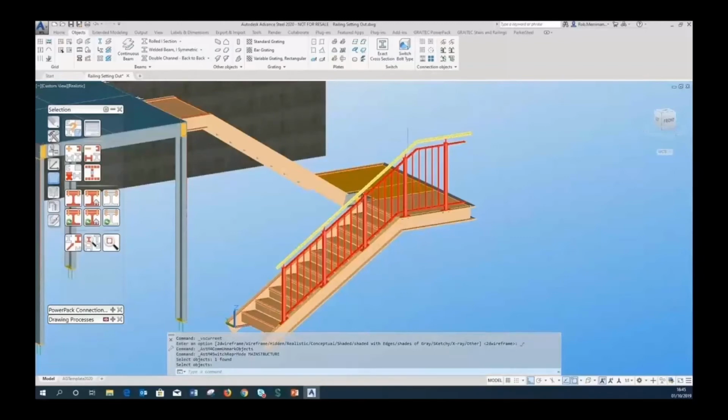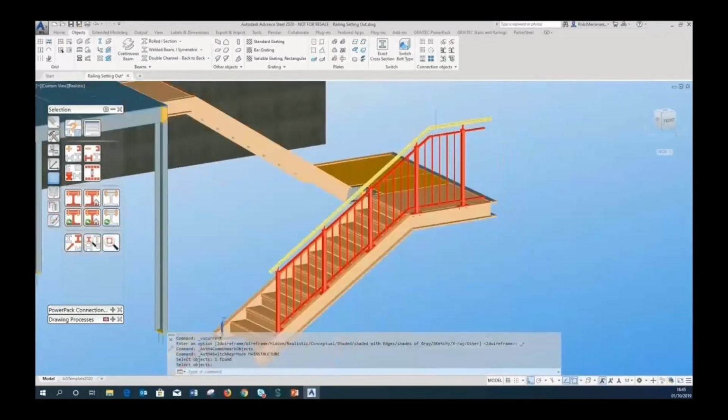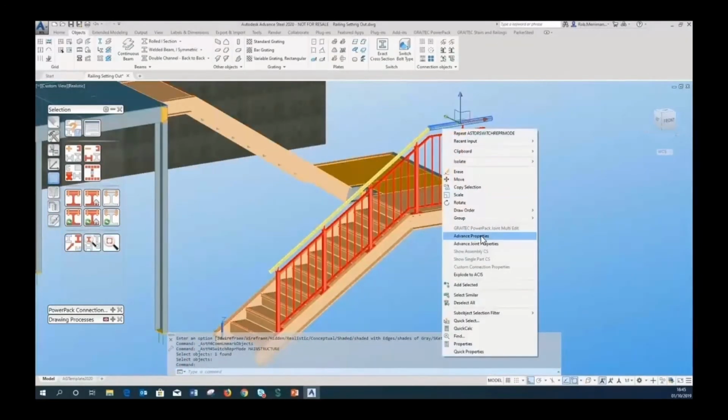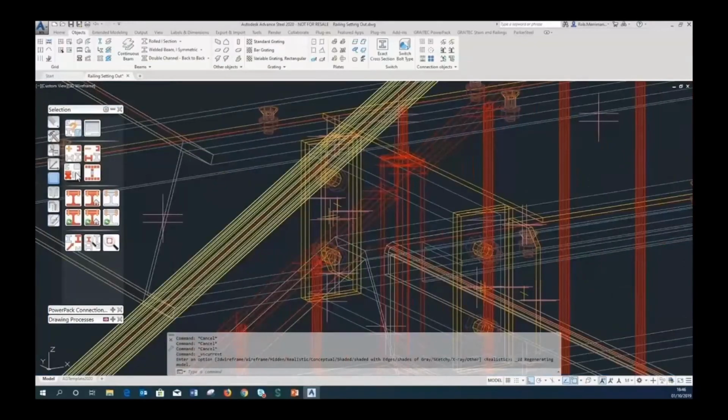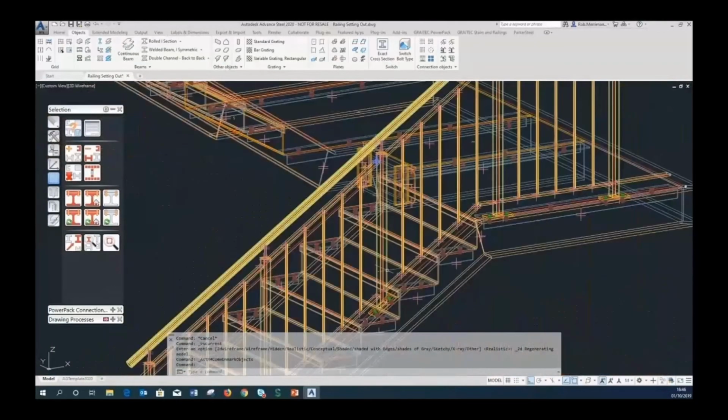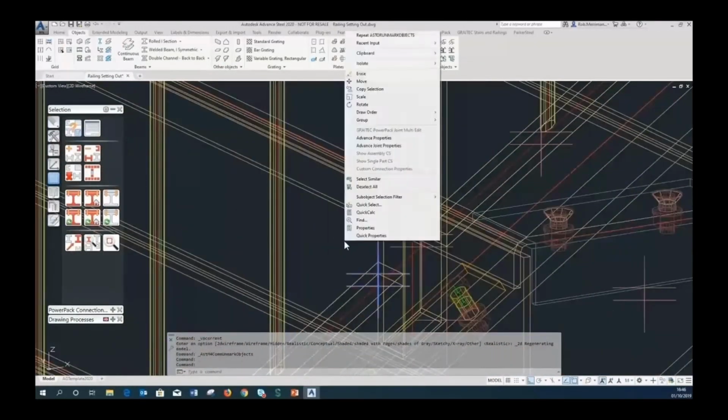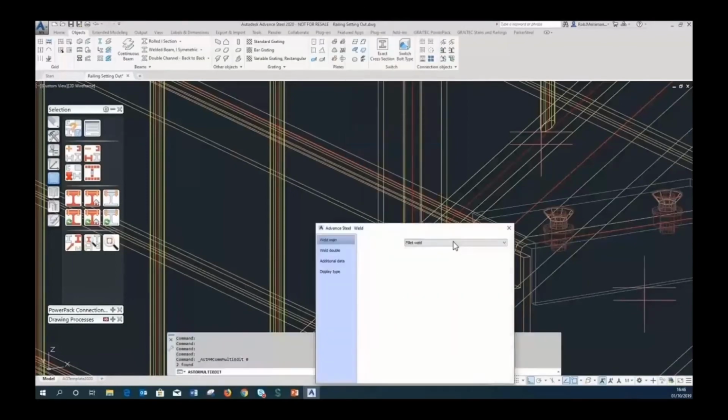So if I select that, you can see now just the bottom bits, the assembly, and the handrails are separate components. So that's handy. I also want to split the bottom portion up though. So I can go to the weld that holds that middle rail, turn off the marking, that holds the middle rail to the post. I can select those two welds and set those to site welds as well.